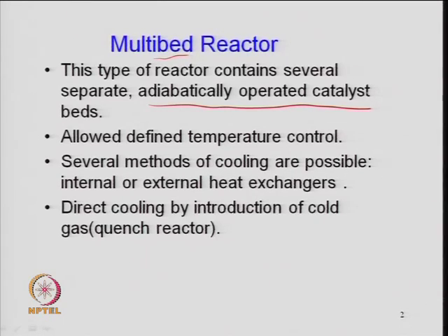So, hot spot formation may be an issue. So, I told you that when the temperature at a localized point becomes very high because of the exothermic reaction, so it will damage the catalyst. So, catalyst can be stable only up to a certain temperature. So, that is very important, that how to make the catalyst stable for a longer period of time during a catalytic reaction, and that is very important when the reaction is exothermic type of reaction. So, runaway problem may also arise, some kind of transient condition, unsteady state condition in the reactor.